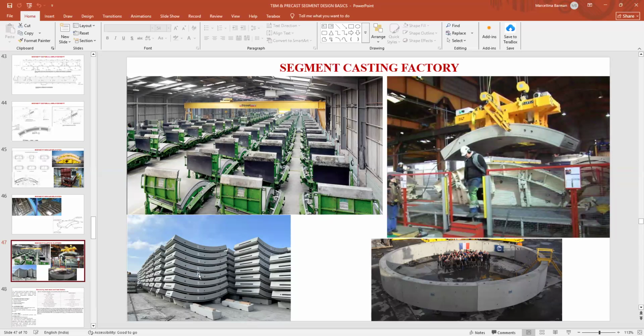So the segments are stacked here. Between each segment, you can see some wooden planks are placed, so one segment is not in direct contact with another. All the loads are distributed to the wooden planks, so the loads are not getting directly in contact between the segments.